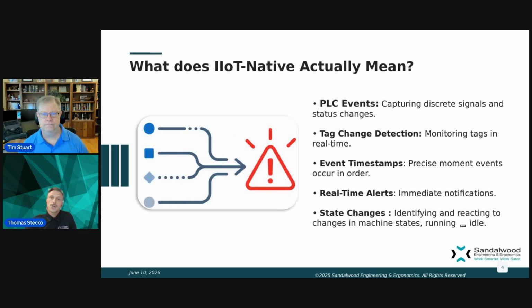So let's say we trigger an upper SPC limit for power, nominal is 1,000 watts. Min 800, max 1,200. Anything outside of those parameters, we're going to get a fault. What do we do with this fault now? Maybe I send a text message. Maybe on your phone you get a notification that you can open and view on a dashboard that fits your phone in a responsive container